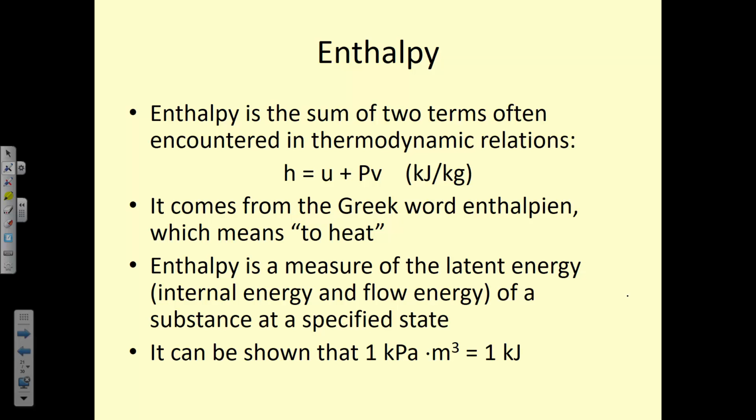It comes from the word enthalpian, which means to heat. And so we're measuring this internal energy and flow energy, which is considered a latent energy, meaning it's an intrinsic part of the fluid itself. Enthalpy is not energy that we've added to the system through work or by adding heat. We can change the enthalpy, but fluids themselves have this latent energy associated with them, meaning that they have some given internal energy state, plus because they're moving, there's some energy associated with that flow.